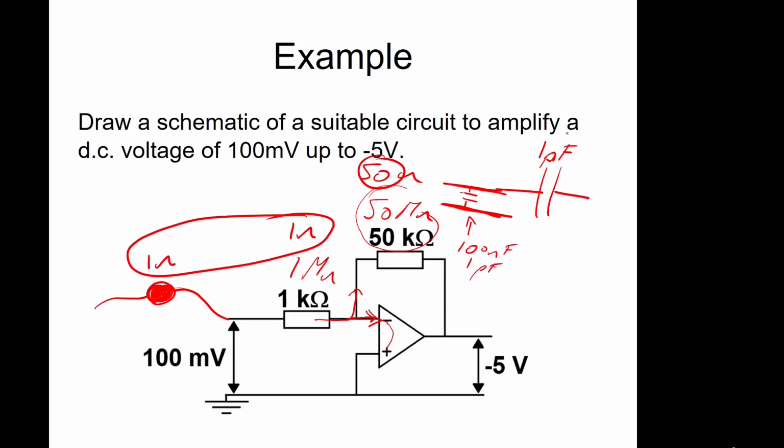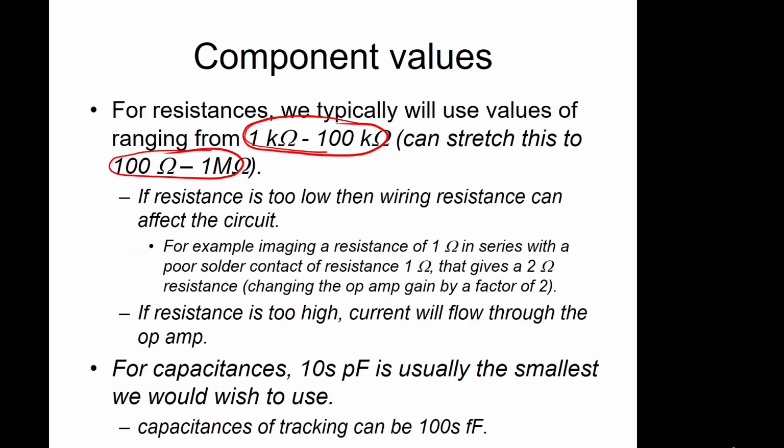So if you use very low capacitances, again, you have to worry about capacitances in the rest of the circuit just with the lines being close together. So capacitors should also be a relatively large value to get around these potential effects. So when we come to talking about capacitances as well, use tens of picofarads up to nanofarads in your capacitors in your circuit. So that's just a bit of practical advice when you ever come to build these circuits.